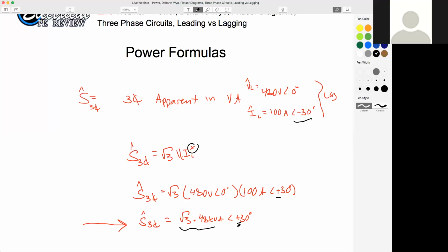M. Walker said magnitude only. She's the, M, I'm hoping that stands for Mary. I'll say M. Walker is the first person to answer this correctly. Sarab said 48 kV. No, Sarab, we are solving for three-phase apparent power, and we know when we multiply volts times amps, we'll get our volt amps. Kahina said conjugate and needs to put in complex form. So okay, we got the conjugate. Technically, this is complex form. It's complex polar. Raymond said this approach is incorrect in case of single phase.